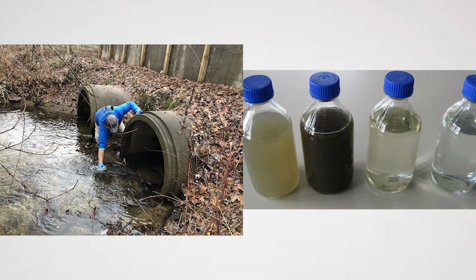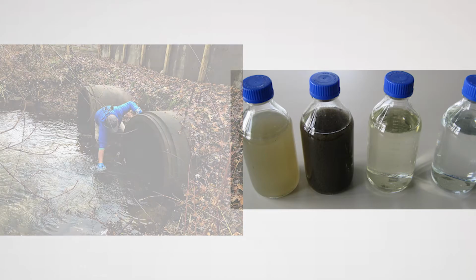In many communities, the wastewater utility will collect effluent wastewater samples from a manhole outside the facility. The samples are tested for key wastewater parameters, which sometimes include biochemical oxygen demand, suspended solids, pH, and fats, oil, and grease. If those parameters are significantly higher than typical residential wastewater, surcharges will be added to the bill.